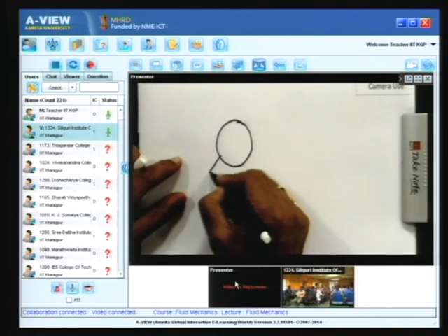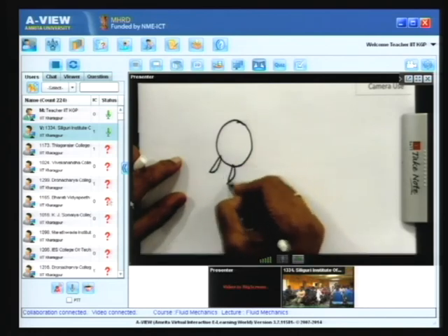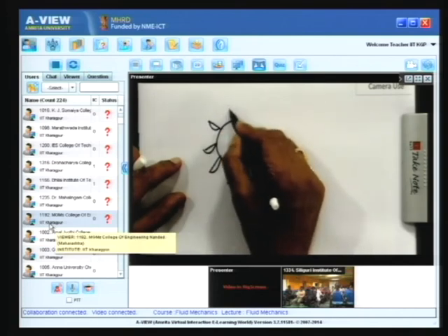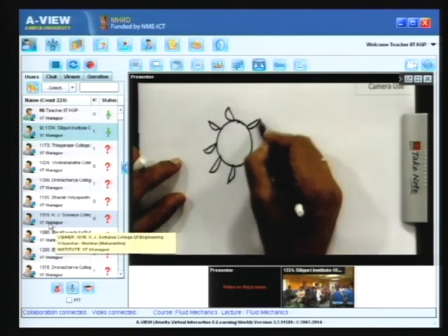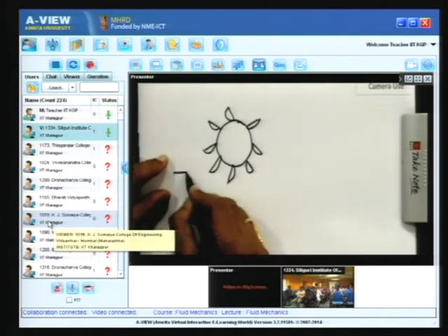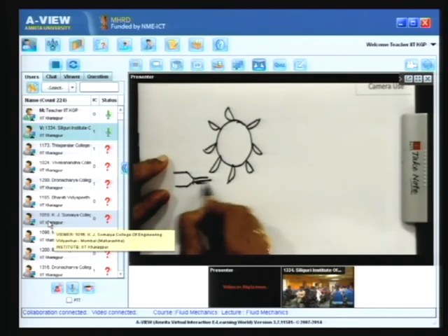I just tell you, if you are interested, the Pelton wheel is like this. This is the blade. This is the blade. These are the vanes of the Pelton wheel. A diagram like this, and a nozzle, there are a number of nozzles, usually 6 to 8 nozzles. They issue the jet.